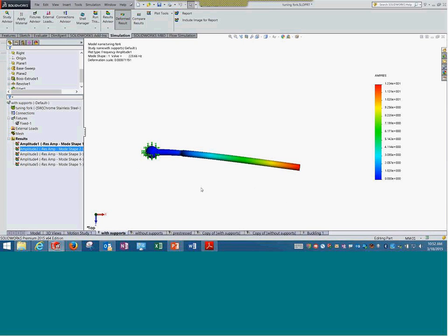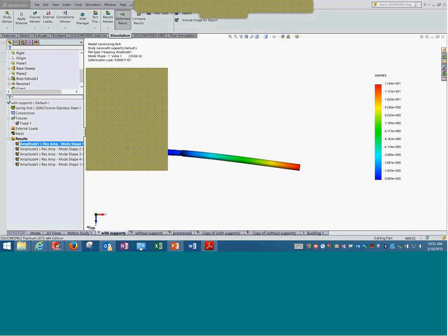So it is actually the first mode itself. Typically, the buckling will happen in the weakest direction, and when we do the natural frequency, obviously it is correlating to the first frequency itself. The shape, I can see, is absolutely matching here.